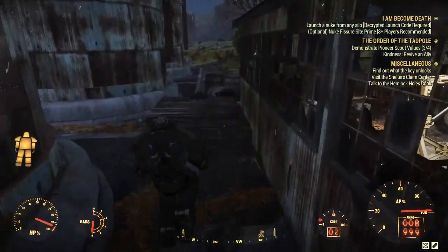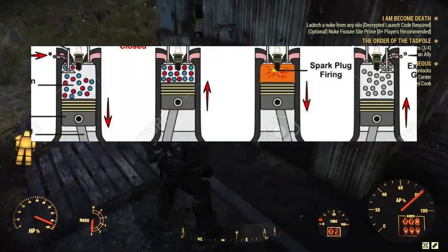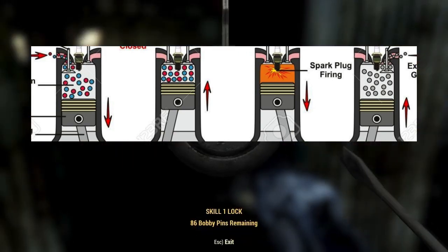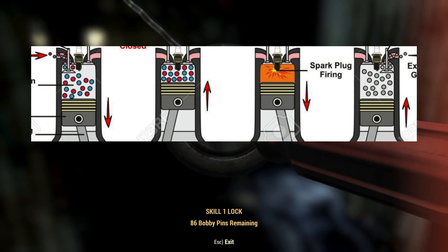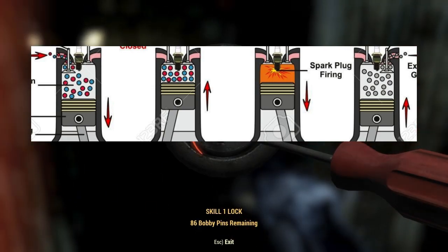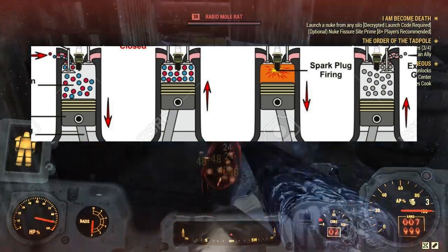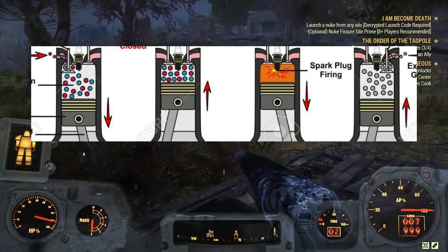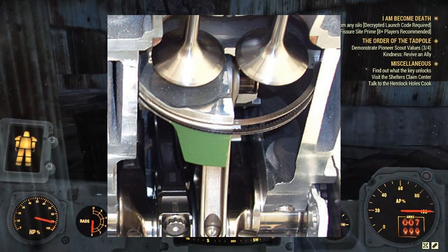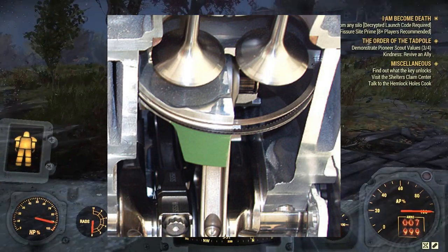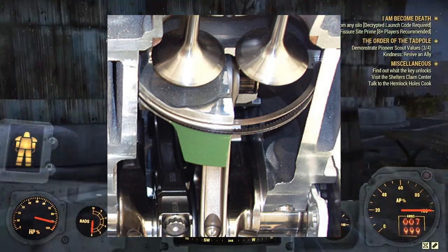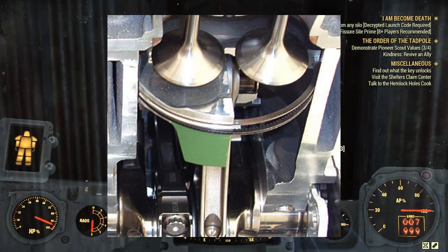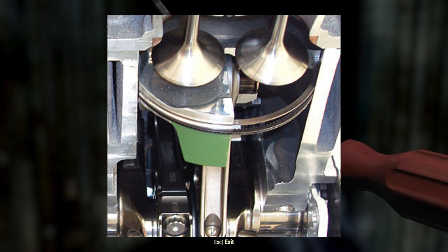And when people describe piston rings as fried or broken, or it blew the rings, or the rings collapsed, what they are talking about is that the piston rings have completely closed. They basically stop filling that gap, and they let the piston just move up and down as if they weren't there to begin with.